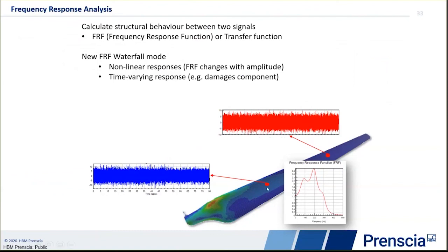You can see there are two signals captured here, the excitation as well as the response. You can compare these two to monitor how the structures behave. Another way is shaker testing to see the modal parameters, with an excitation and a response. You can see the gain as well as the phase.